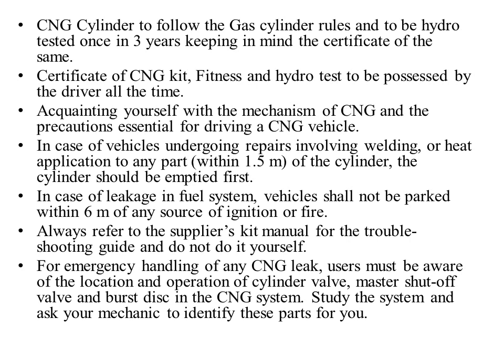In case a vehicle that has been fitted with CNG involves repair, like welding or heat application to any part, the cylinders should be emptied first. And in case there is a leakage in the CNG fuel system, the vehicle shall not be parked within 6 meters of any source of ignition or fire. And of course, always refer to the supplied kit manual for troubleshooting. If there is any trouble, it is preferable to refer to the kit manual that has been supplied with it, and we should not try to fix it ourselves. A qualified person should be called.